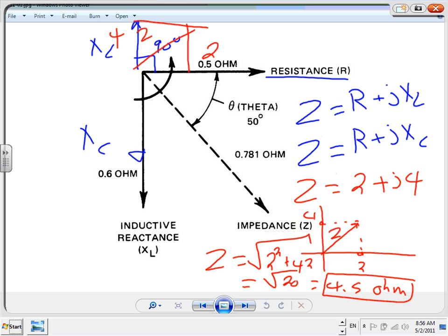All the motors, all the transformers that you put in a building, it's an inductive load. So most of the time, 90% of the time, you're going to be in this situation. The triangle is down, guys. And to correct the power factor, we need to move it up, to move that leg up. How do you move the leg up? By adding more capacitance, or capacitive reactance.